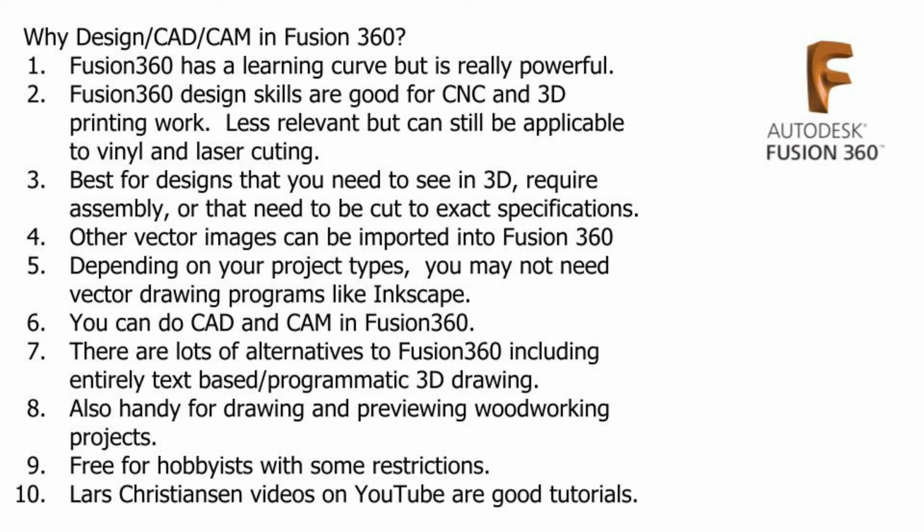You can import other vector images that you might draw in Inkscape or other programs into Fusion 360. And one place where you might use Inkscape instead of Fusion but combine them is for something like the horse image that was used earlier. That would be very hard to draw in Fusion 360, but very easy in Inkscape. So you might do it in Inkscape first and then import into Fusion 360. You can actually do your computer-aided design and computer-aided manufacturing within one program in Fusion 360.